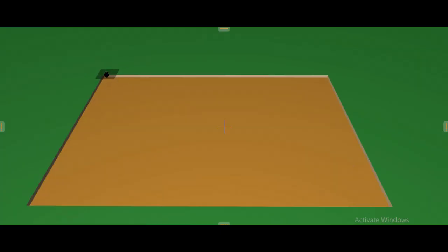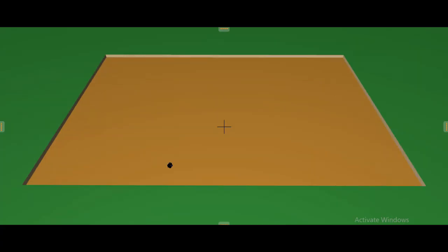The length will be from this corner to this edge, 12.40, by a width of 8.40, that is from this corner to this corner. I first of all book that, and then I square this length by this width, which, if you refer to that, was giving us 104.16. And the same area, I'm now writing it in the squaring column.